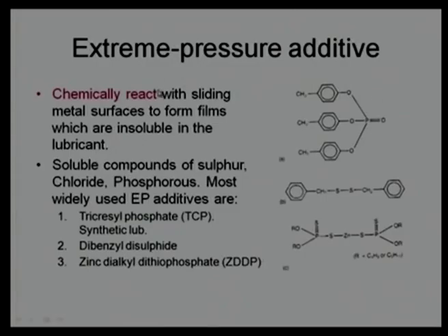They are basically boundary agents. They chemically act with the surface, they corrode the surface, and make a very thin layer on the surface. That corrosion is done purposefully, which is why we call it a sacrificial layer. The sacrificial layer is made immediately, to avoid future corrosion or future deterioration of that surface. So, they act as a wear resistant layer.